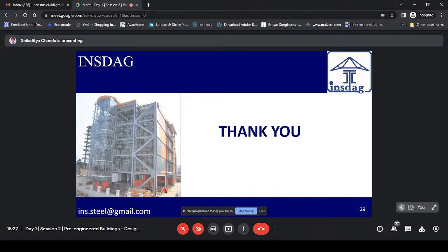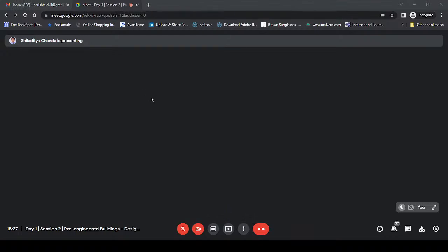Another major thing is load. I can give you one example, IS 875 part 2. Since in most cases of pre-engineered buildings the slopes are less than 10 degrees, you cannot allow any live load reduction at the roof, even for an inaccessible roof. In IS 875 the load is 75 kg per square meter, but if you refer to MBMA, you can have 57 kg per square meter. So in the live load case alone there is a reduction, 75 in the IS code and 57 in the MBMA code. By following MBMA, people get a lot of economy.